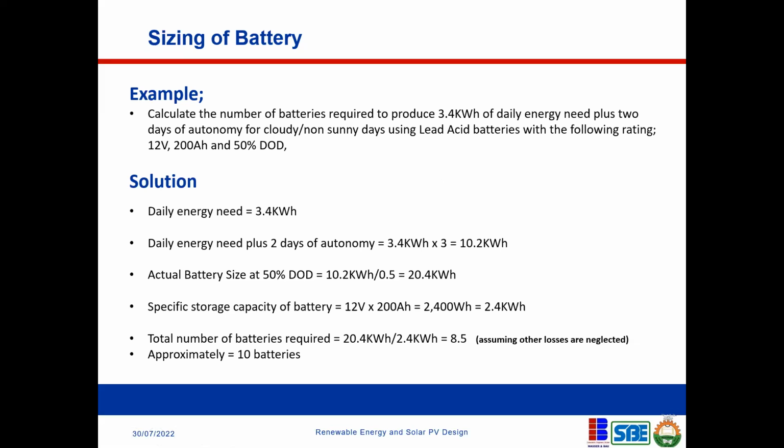When you connect two batteries in series, yes, that's 24. But when you now connect another 12 volts in parallel with that series connection of two batteries, you will not get an equivalent voltage of 12 volts again. When you connect two batteries in parallel, the voltage remains the same. It remains the same, yes. That's when all the voltages are the same.